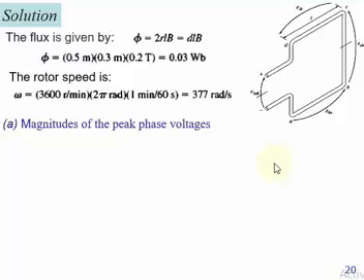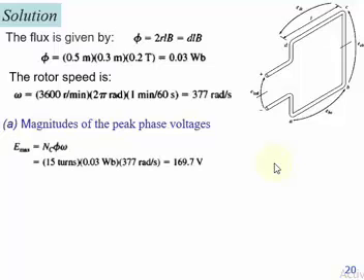First of all we find φ and ω so that we can put these values in the formula to find the maximum induced voltage E max, as shown in part A, that E max is equal to Nφω.